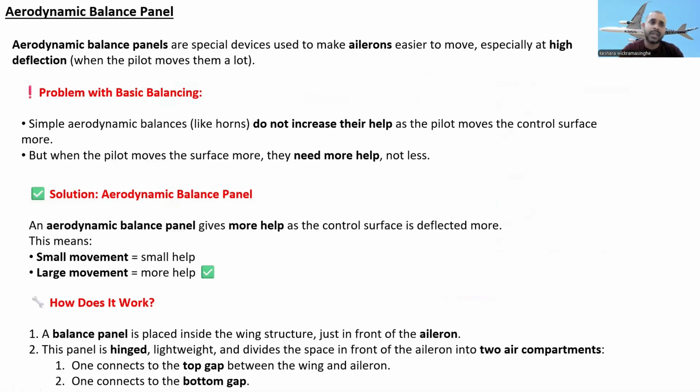Okay, so the problem with the basic balances: simple aerodynamic balances like horns do not increase their help as the pilot moves the control surface more. But when the pilot moves the surface more, they need more help, not less.